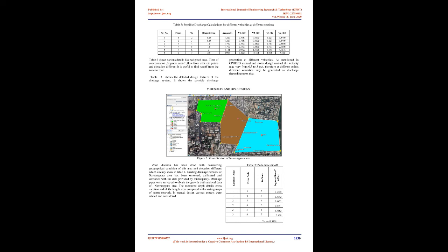B. Elevation Profile. In this, Google Earth Pro is used for measurement of elevation as well as elevation difference of the Navrangpura area. The whole area was divided into 3 zones and 7 node points were taken. With the help of the line tool, create a line which joins the 7 node points, and through the show elevation profile option I got the elevation of the whole area, which is shown in the figure below.